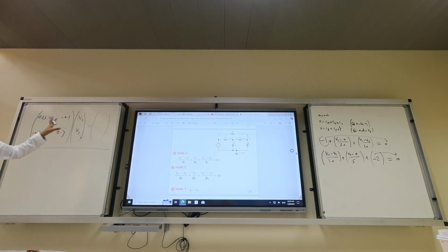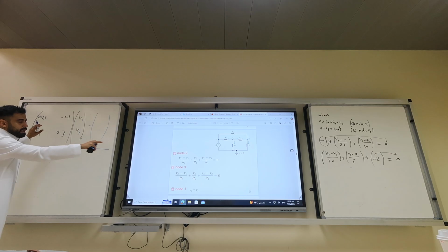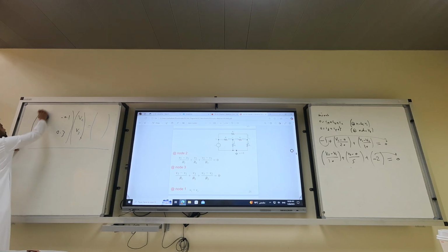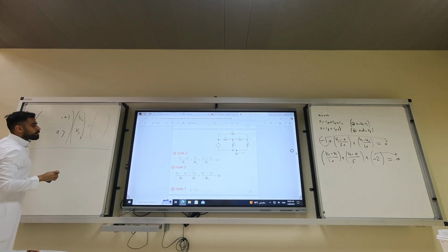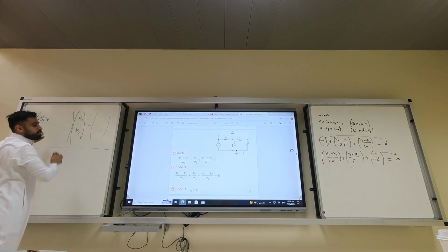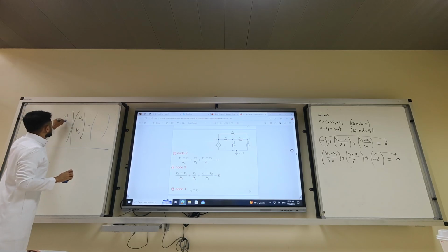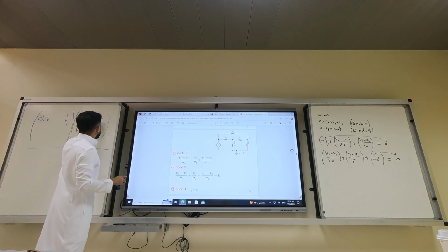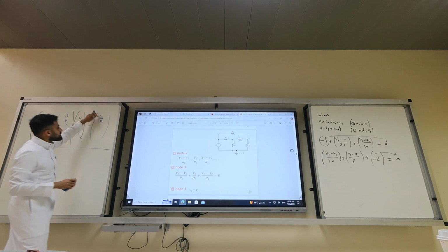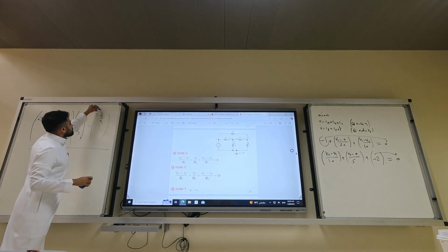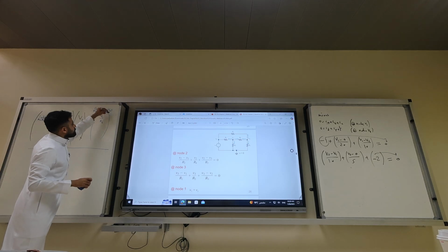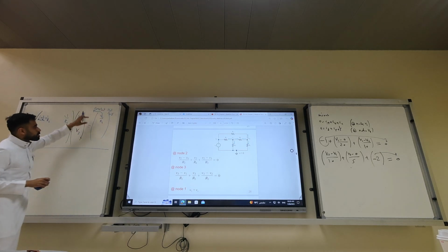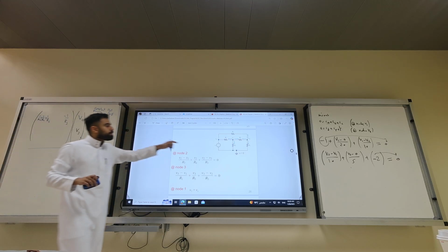Now, I'm not going to do it because it has too many variables, but the key here is, for V2 you have 1 over R2 plus 1 over R4 plus 1 over R3. For V3, what do you have? Minus 1 over R3. Equals to 1 over R2, and then you include the V1 here. V1 is constant, not variable, okay? This is a constant, it will be 5 volts. So in a numerical example, this will be 5.